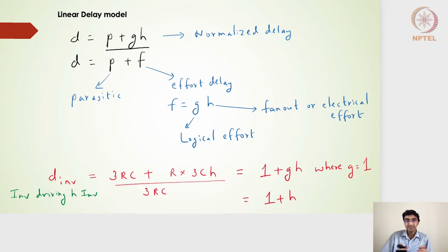So the delay we estimate will not be a non-linear function of the capacitance or the scaling. It is a very linear model. When I write the lowercase d, it means a normalized delay: the absolute delay for a particular gate divided by the inverter's delay.